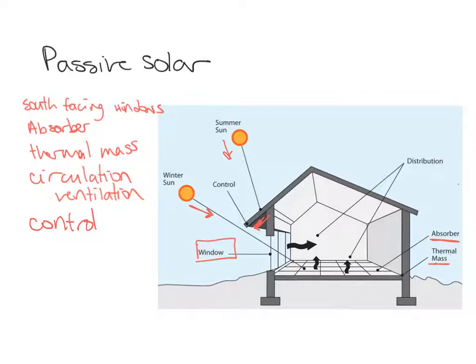Trees near the house can also shade the house because in the summer they'll have leaves that offer more shade, and in the winter they will lose those leaves, allowing more light in that can heat the house. You can also get some daylighting through passive design. So using natural light by your placement of windows, you can have skylights that can bring in some daylighting, but that will also, if you have skylights in the roof, allow the summer sun in. So if you are trying to keep the house cooler in the summer, that might not be the best idea.